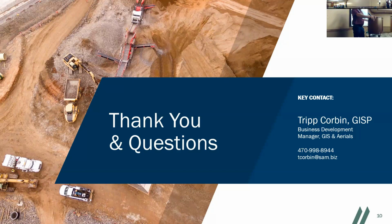One of the questions I had was mostly for MicroStation, when we're bringing in a lot of DOT files. We work for the tax administration, trying to get the new right-of-way lines and stuff like that. On the larger projects, like the I-95 expansion that goes county line to county line, they use a lot of localized stationing, and trying to get DOT to reconvert those files to NC grid doesn't always work. So the projections never quite come in right, especially if you're trying to do geoprocessing. Are there any tricks that you know of to get those processes to work?